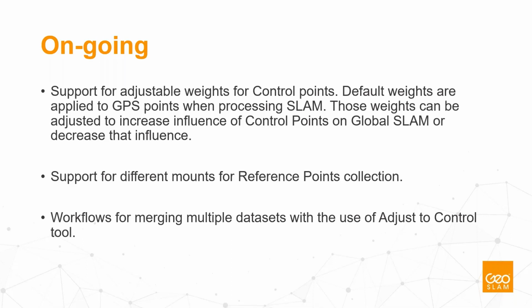We are looking at supporting different mounts, so not only reference plates. Hopefully we will be able to do that. There is a limitation at the moment because we are applying transformations that are calculated from the reference plates. And there is still ongoing work towards workflows for merging multiple datasets with the use of Adjust to Control. I mentioned that very briefly, so I don't propose that as a workflow at the moment, but it could be possible for repeated surveys on stockpiles or on the mine where you want to have separate data that will be coming and matching to each other.